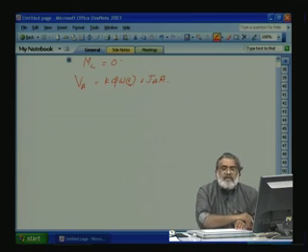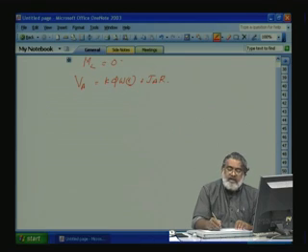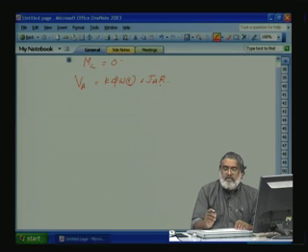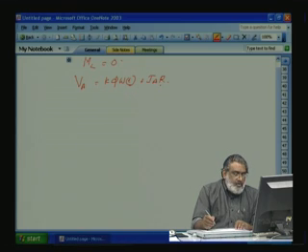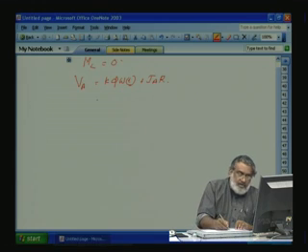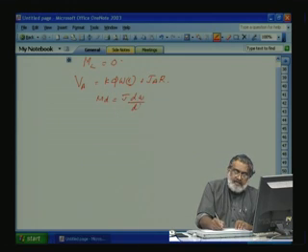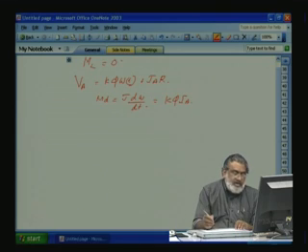So, here we have removed the inductance part, because through the controller we are giving full current. We are controlling the current IA and applying the VA, full DC, assuming the leakage inductance is negligible. Now, L is equal to 0. So, the driving torque MD for acceleration is J into d omega by dt. Okay. This is equal to K phi into Ia, K phi is constant, this is our driving torque.